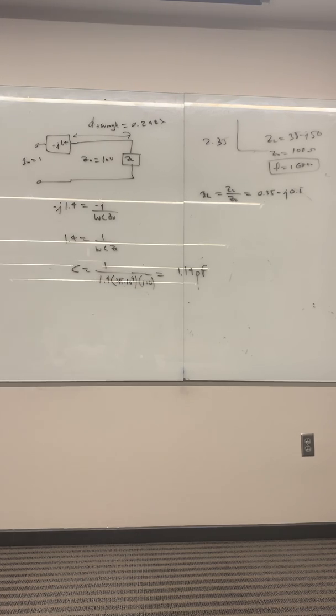Now we have to calculate this distance from here all the way around. We know if we go all the way around to here, we get half a wavelength, right? So now I take the point you ended up at, which in my case is 0.326 lambda, and we subtract from it the point we started, which is 0.425, right?